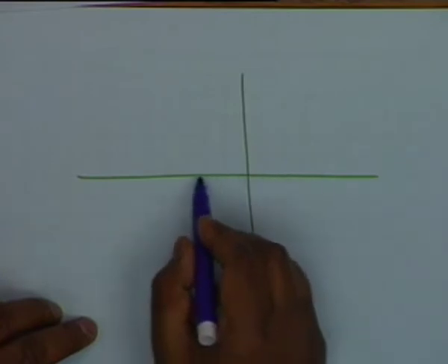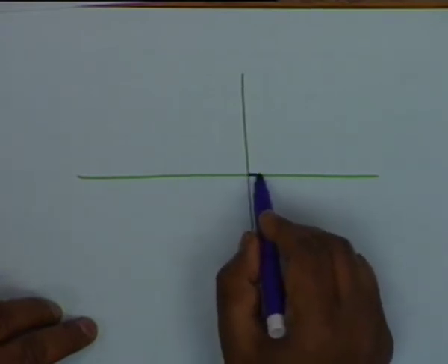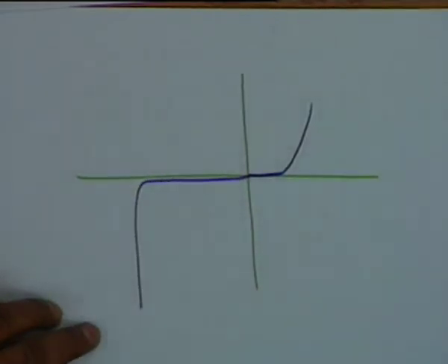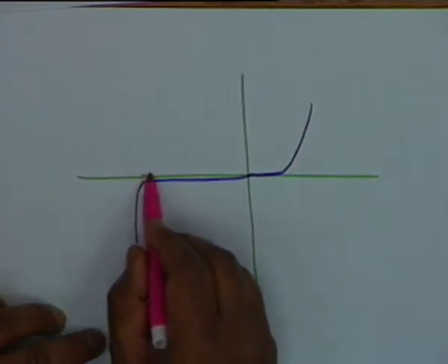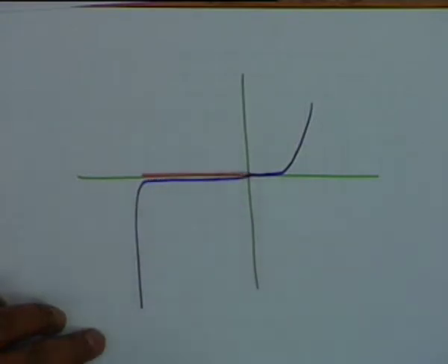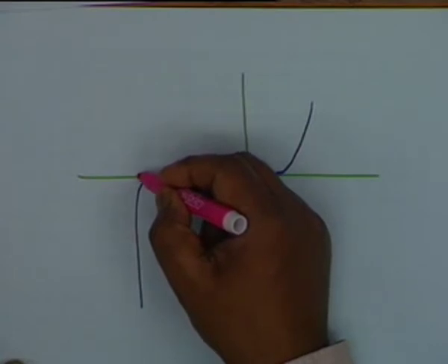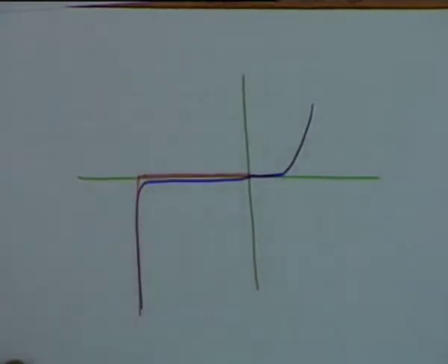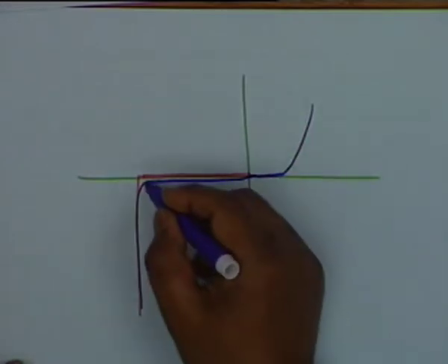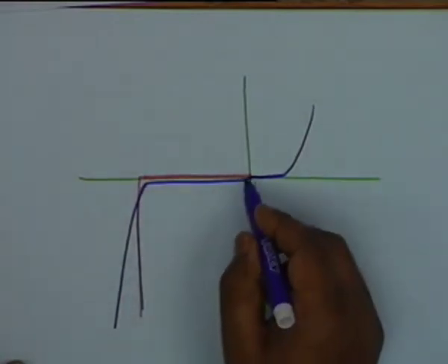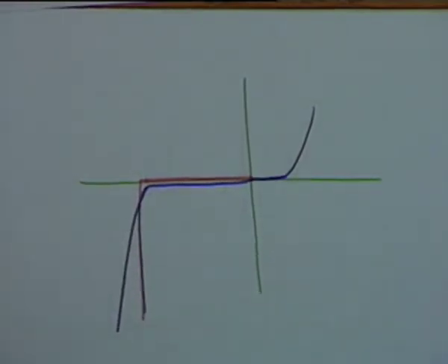A Zener diode is operated in the reverse biasing condition, and one of the models that one uses is this, that is, one approximates this by means of zero current. I is put equal to 0, and then a vertical line like this. I must tell you that the actual characteristic is like this, not a vertical line. This is the actual characteristic. It has a finite slope.